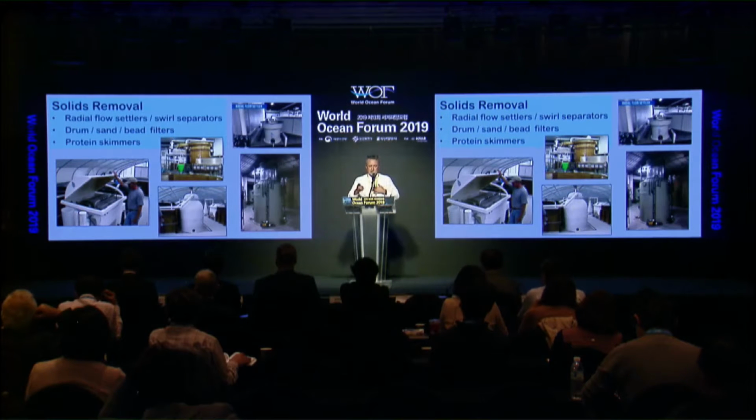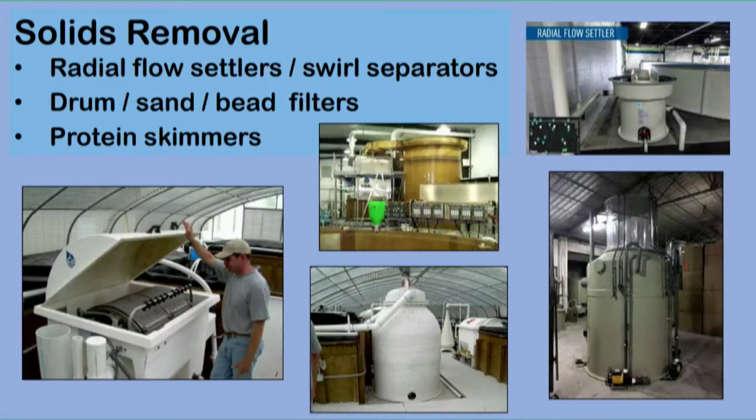Of course, we had Mr. Heinrich describe his drum filters for solids removal. For fine solids removal, we use protein skimmers, which I'm sure many people have seen on their fish tanks at home or in aquariums, where they get that display quality water. They use the foam fractionators to remove the fine solids. And as Mr. Hahn presented, but I don't think he got a chance to talk about it, was using ozone with the foam fractionators or the protein skimmers to help remove those fine solids and keep that water display clear. It's also very healthy for the fish.